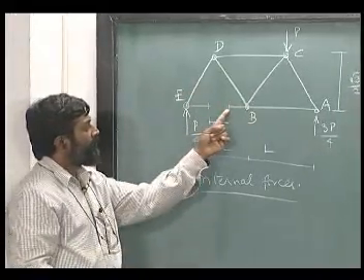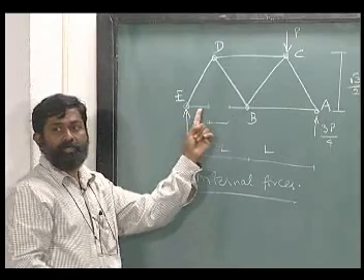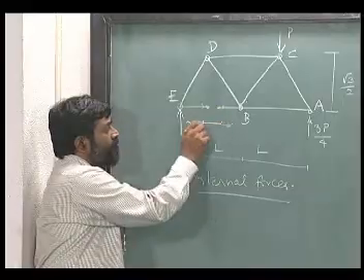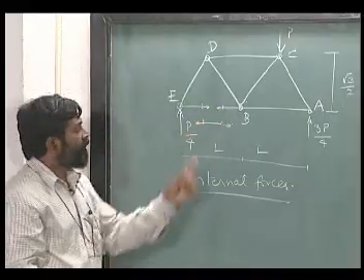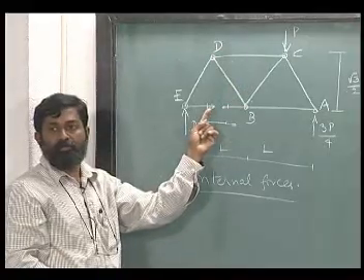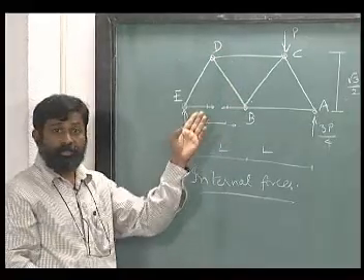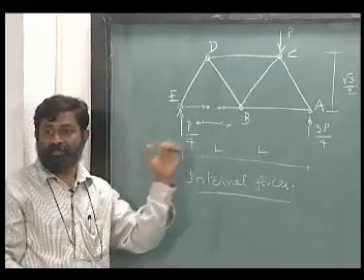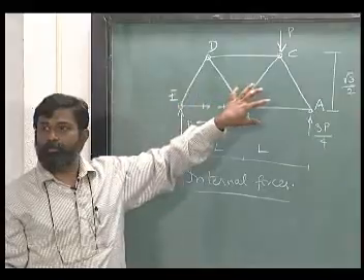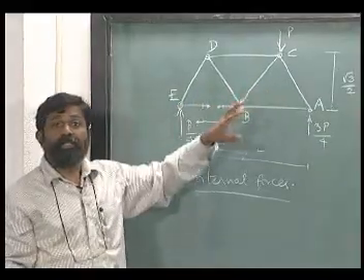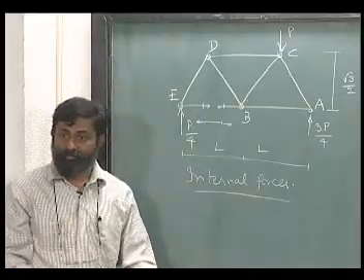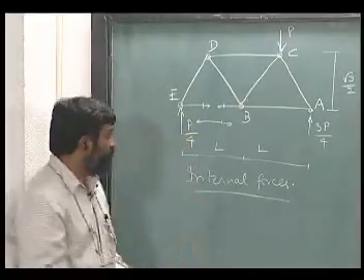I will have equal and opposite forces acting on this like this, right. Since they are equal and opposite in the structure, I will not be able to solve for this internal force. This is an important thing to understand. So if I can extract a free body out of this entire body, then it is possible to write down separate equations from which we can solve for internal forces.